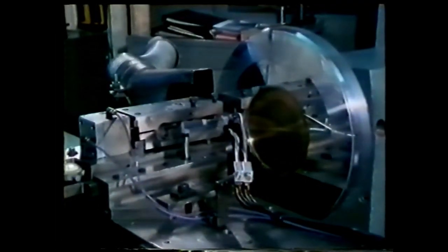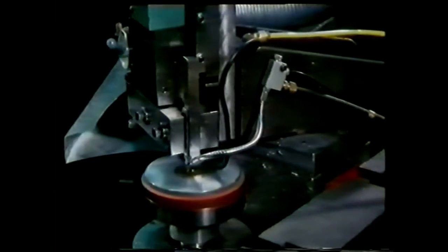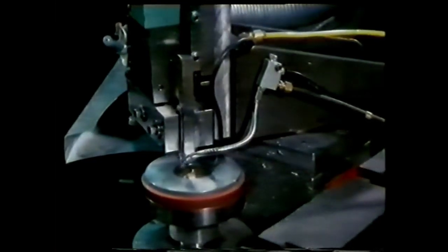When the appropriate stones have been selected, they're carefully mounted, making sure that they're properly aligned. Diamond tools are best used on vibration-free equipment, such as this lathe, which is specially designed to put the finishing cuts on aluminium computer memory disks. To give the discs the best surface finish possible, cutting speeds are very high. In this case, over 4,000 revs per minute.